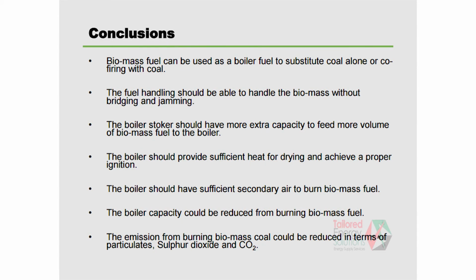The boiler should have sufficient secondary air. Because of the high volatile matter, again, you need more overfire air available to attack the gases emitted from the fire. Boiler capacity can be slightly reduced, with better emissions.